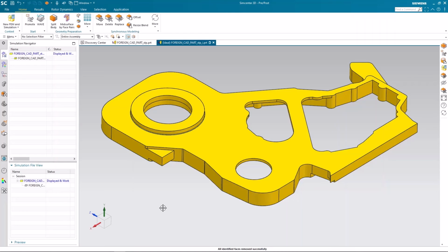So it is good practice to consider real-world operating conditions for simplification of our CAD geometry. In our case, for simple structural analysis, we do not require any holes. We are going to consider all holes filled with the same material. So it is good practice that we consider real-world operating conditions during simplification of our geometry.